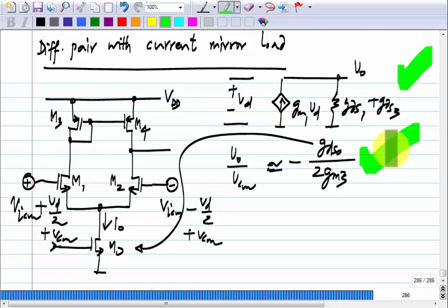Now, we can apply signals to this and then we can use this itself as an op amp. It is not a great op amp because, first of all, the gain is sort of limited to about 100 or so, and the output resistance is not very low. So, if you load this with a resistor, the gain reduces further, but still in some situations, if you do not have a resistive load, you can use this. As an example,